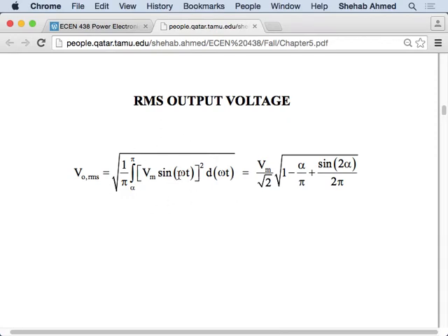for any waveform, right? Like the waveform that's in the exam, it's a simple square wave. RMS value is something easy to calculate because it's areas under the curves, right? You can easily calculate areas under a square or a rectangle or a triangle. So the integration will be easy because it's flat, integration of 5 squared. It's a constant, right? So if I give you something, it's not going to be complicated, but it's going to be testing your ability to apply the theory that we studied in class. I'm not quizzing you on your ability to integrate and use the cosine rule and all the trigonometric relationships that I don't cover in class, right? So I would not give you a difficult integration.